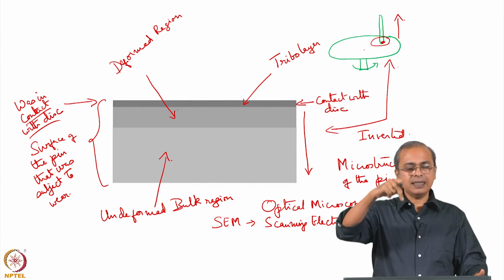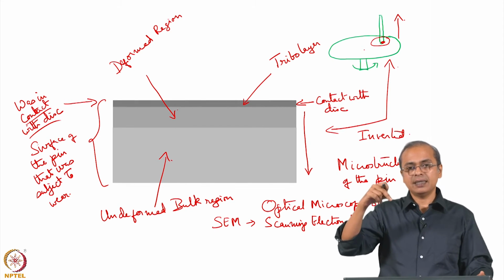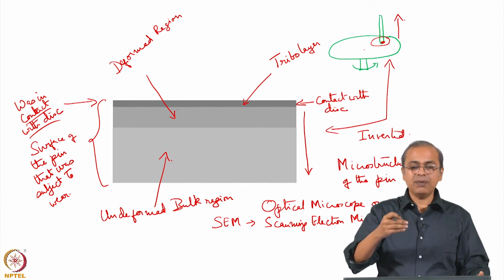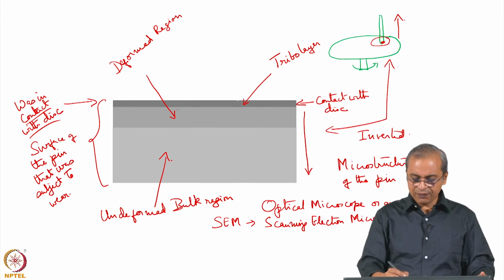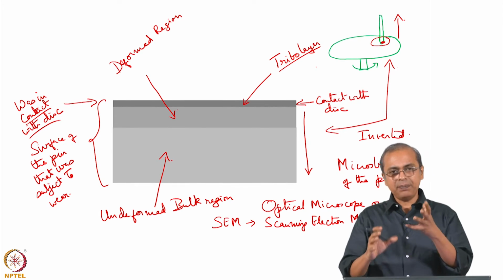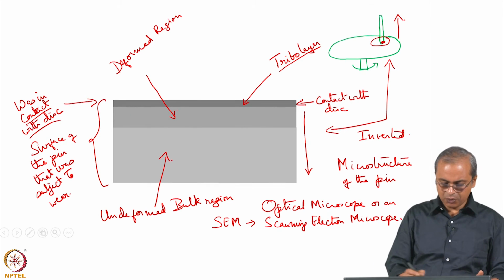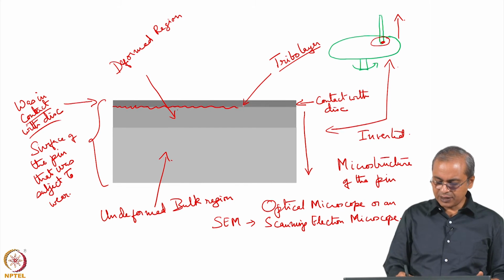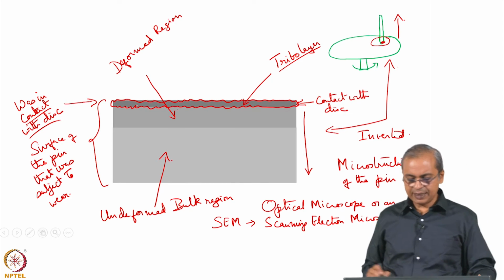The layer that is directly in contact, any kind of oxide layer it has, that oxide layer gets damaged, and then whatever is the exposed layer, that also gets oxidized. So you usually have sort of a damaged, debris-like layer which sits on the top. Even though I have shown you, in this schematic, some kind of a uniform layer, actually it will be a rough layer, a somewhat damaged and uneven layer that you will see out here, and that is your tribo layer.